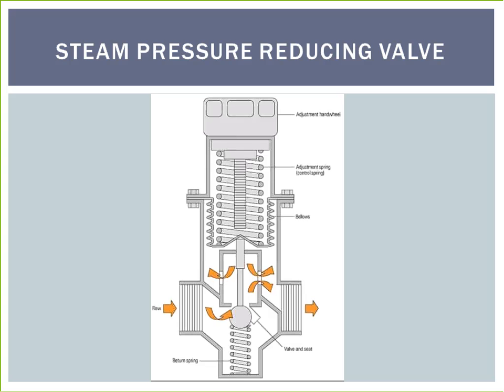It can offer the further advantage of extremely rapid response action by immediately sensing and adjusting based on the downstream pressure. In pressure-reducing valves, the mechanism that automatically adjusts the downstream pressure typically uses the balance of forces between the steam pressure and an adjustment spring. At present, this is a universal concept on almost all manufactured pressure-reducing valves. However, there are two different ways in which this mechanism is implemented to control the amount of valve opening.